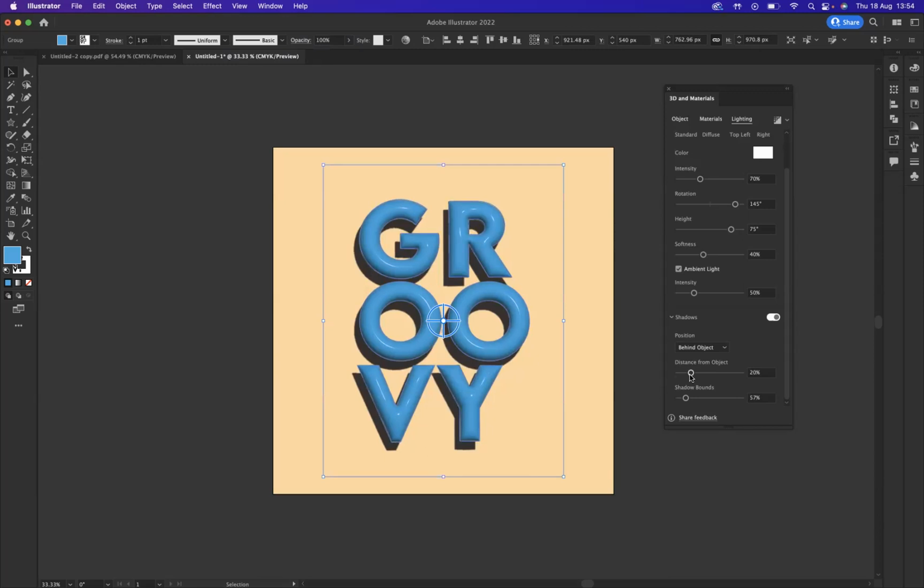Okay, guys, as you can see, we're really getting there now. Now, what I'd like to do is render our image here, our design. So I'm going to come to our option up here. Let's make sure we turn our ray tracing on, quality at low, and I'm going to say render.